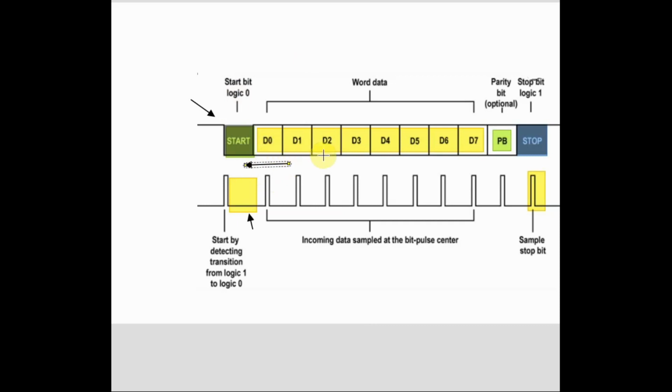So this use of start and stop bits to control the transfer of data is called framing. And after that stop bit, if there is no transfer, then the signal is high, which is referred to as mark, and low is referred to as space. The rate at which serial communication takes place is called baud rate, which is bits per second.